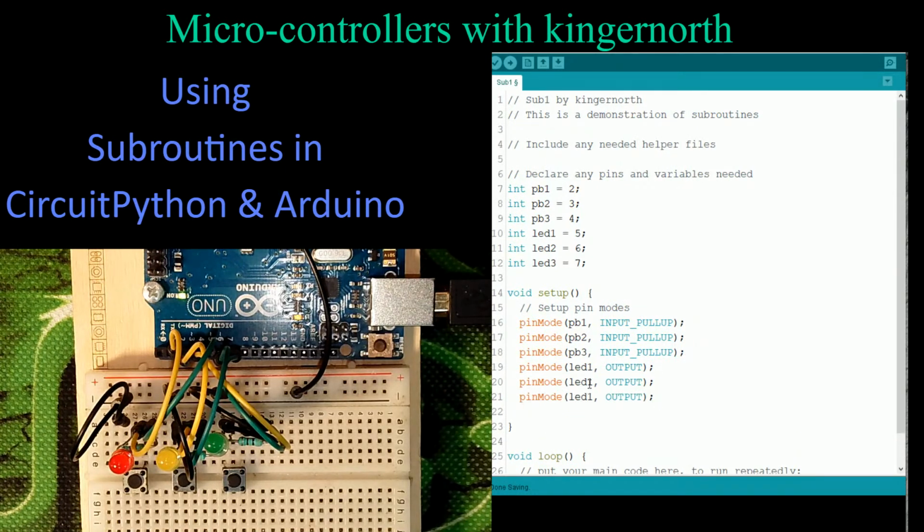And we're going to go ahead and set up now LED 2 and LED 3. So there we go. We have the basic setup done. We now have 6 devices connected to our Uno, and we've set up 6 pin modes for our Uno. So they match. And this closing brace down here, I have nothing after that, so I can get rid of that extra line. And now this is all nicely indented within the start, which is the opening brace, and the closing brace for the void setup subroutine. So that's created that very quickly.